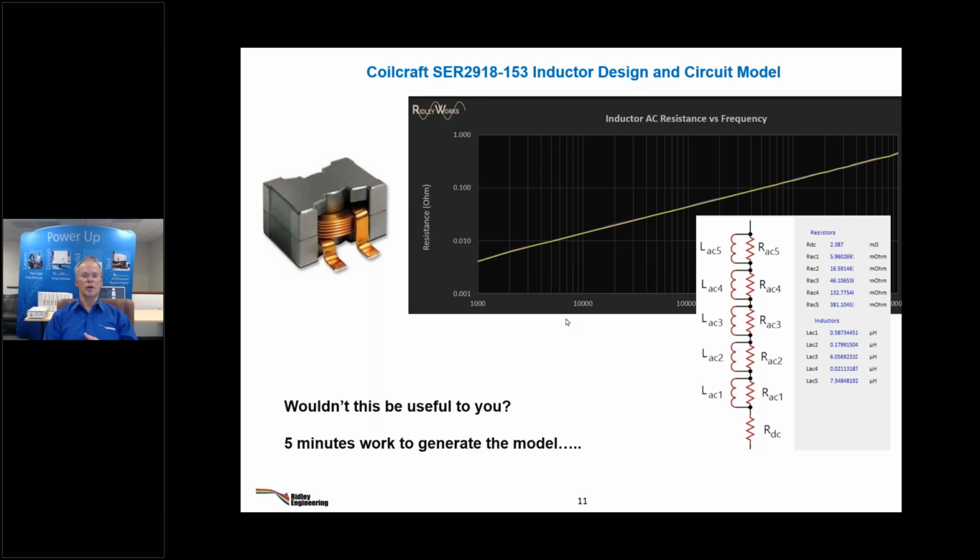What's the main purpose of interleaving with planar transformers? Well, planars are very complicated. If you have primary and secondary with the same turns count, and you put a helical primary with a helical secondary, it suffers the same thing where all the current flows towards the middle. When you change the turns count, the primary is going to pull the currents to different places, and then the only thing to do with that really is to go to finite element methods. So go hire the universities, grab a student and say, hey, can you analyze the structure for us? And if you can send us the AC resistance, we'll send you back the model here.